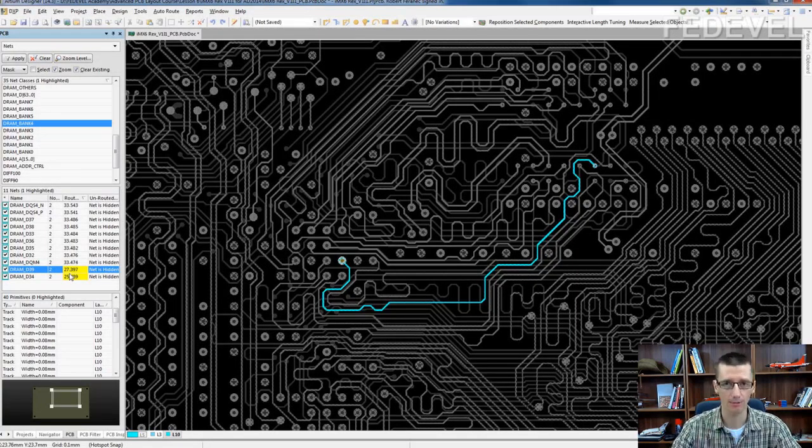Now Altium can do it, and it will use this yellow or sometimes red color to tell you if the signals in this group are in the tolerance of the rule which we just set up. That's not all. Have a look.